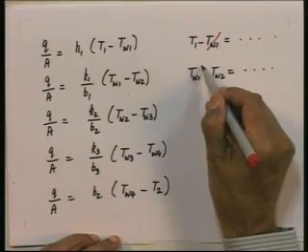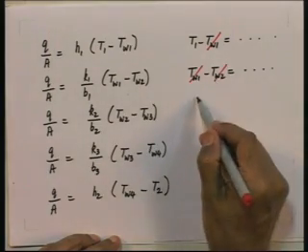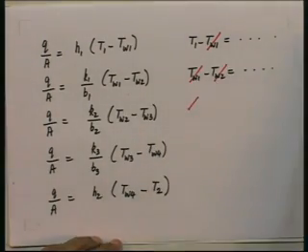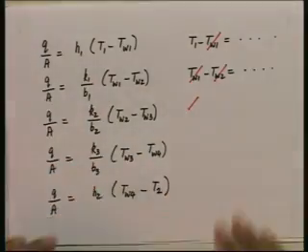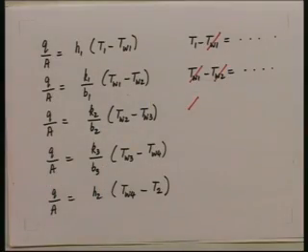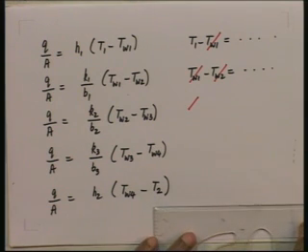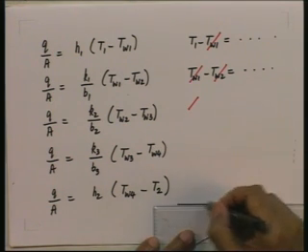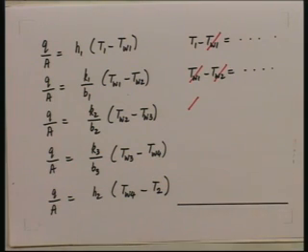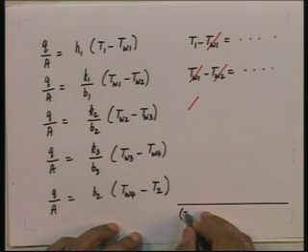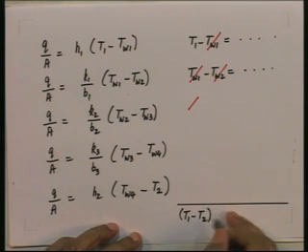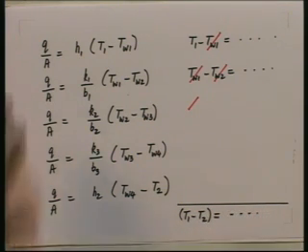If I add up, notice what is going to happen. The intermediate temperatures TW1 will cancel, the intermediate temperature TW2 will cancel, all of them will go, TW1, TW2, TW3, TW4, all will go. All that I would be left with on the left hand side when I add up will be T1 minus T2. If I now add up all the 5 expressions, all the intermediate temperatures will go, and I am simply going to get on the left hand side T1 minus T2 is equal to something. Let us put that down.